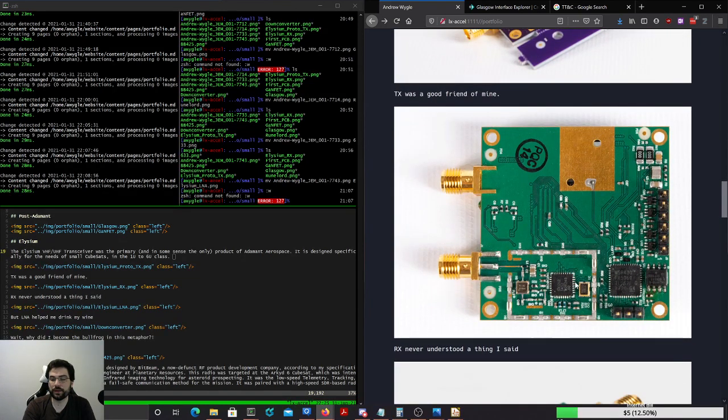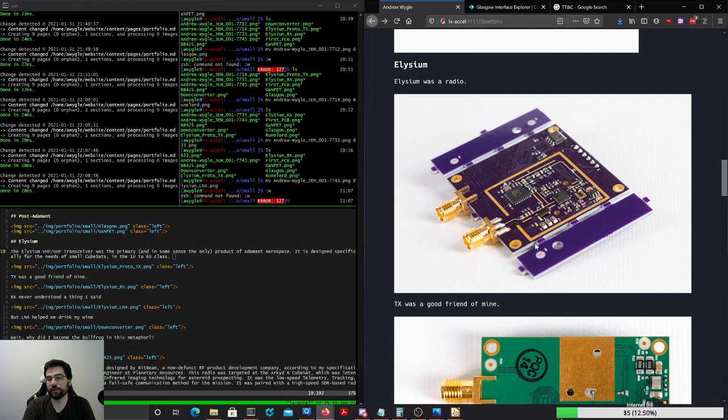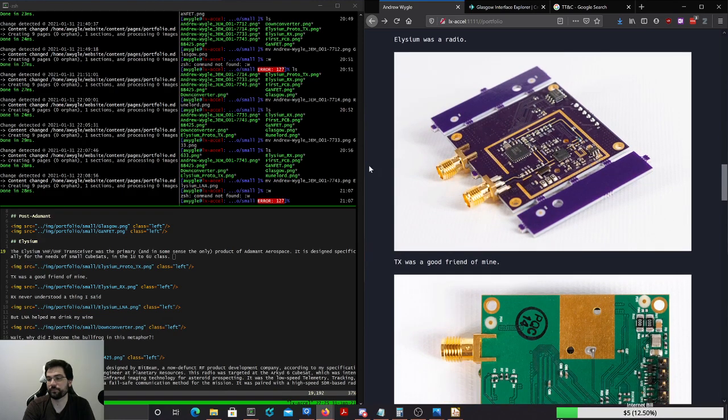And that was one of the main design goals. The other main design goal is that the transmit shouldn't break the power bank either. So the amplifier used is a Class C amplifier, which is fine because it's a frequency shift keying radio. So it's 50% efficient up to 5 watts RF. So that was another major design goal.